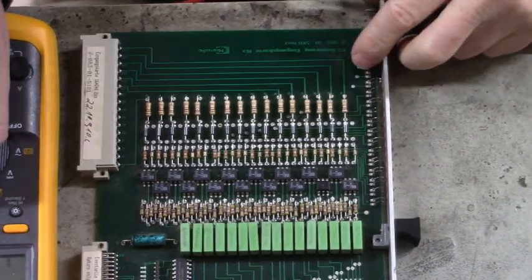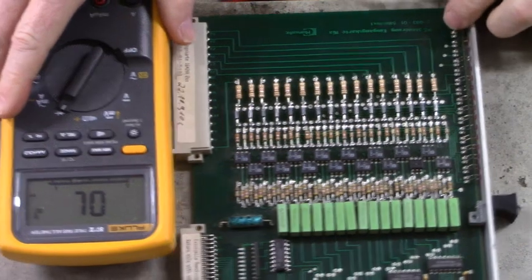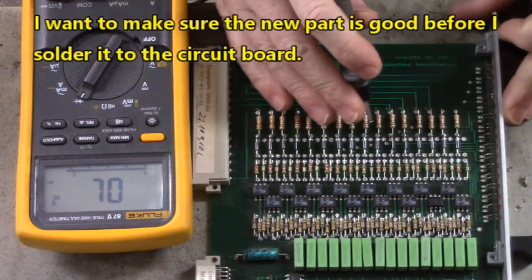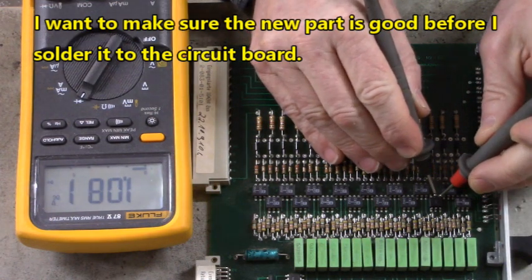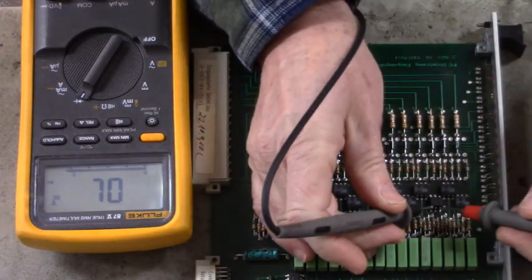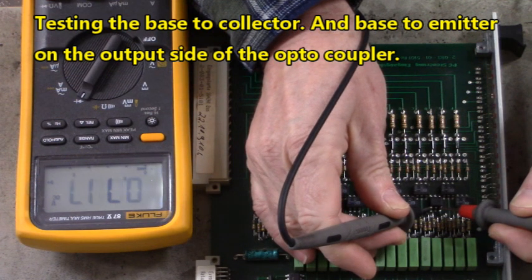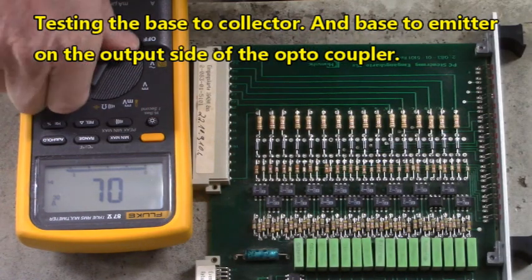Before I solder the new optocoupler on the board, I want to make sure it's okay, so I test the LED input side and the NPN transistor output side with my DMM set to diode voltage test. That's a good optocoupler.